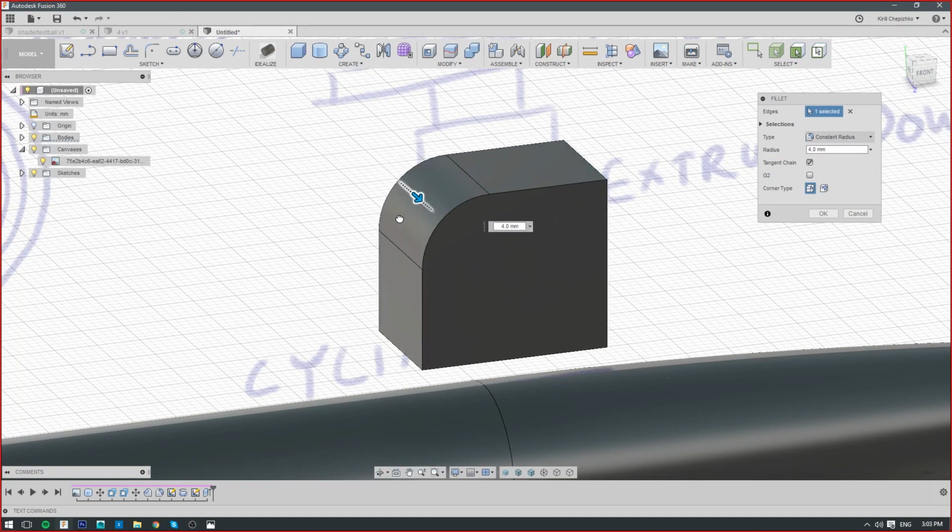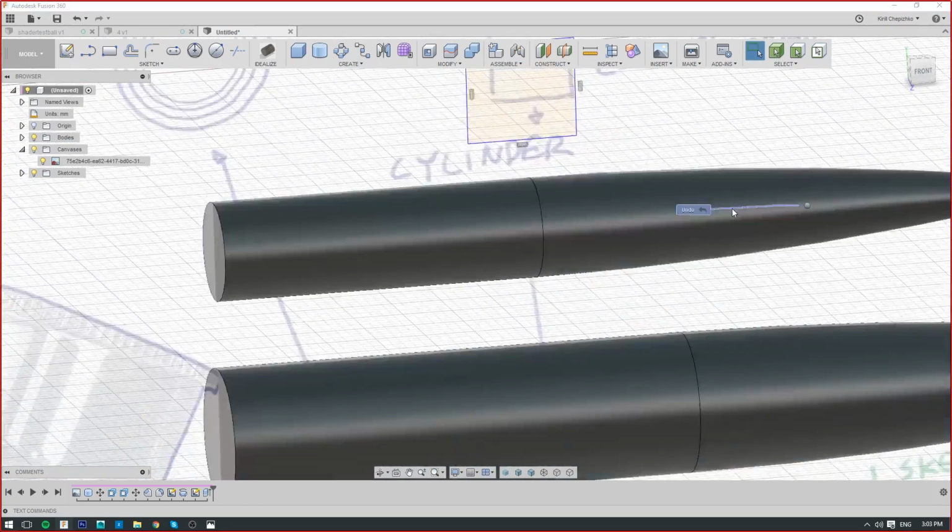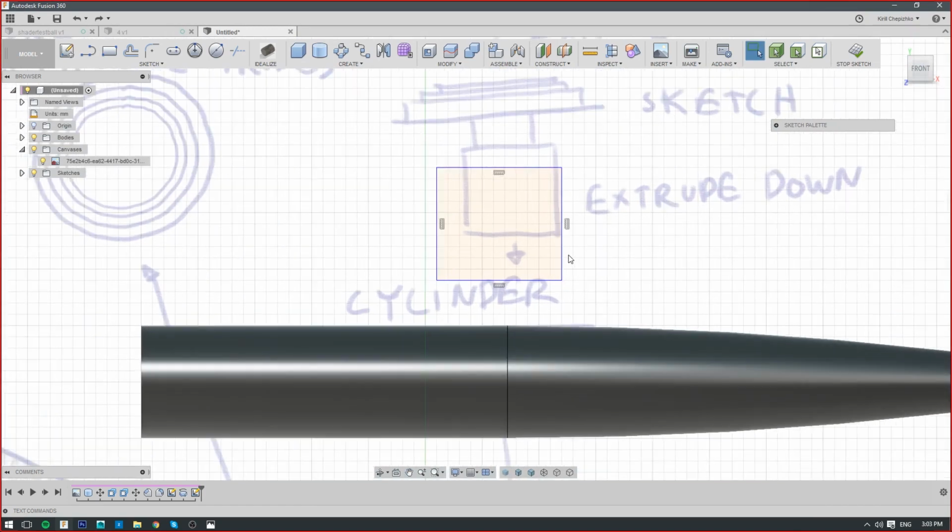So it really depends on what you know. Having all those little extra lines on the sketch will end up showing in your geometry later if you missed that. And it's easy to miss, because at this level of zoom the fillet might look okay.